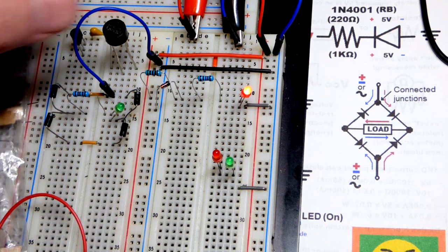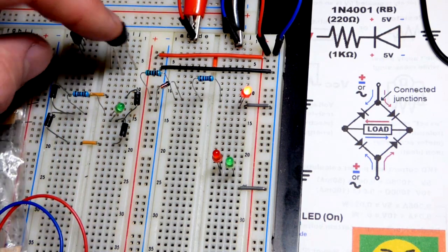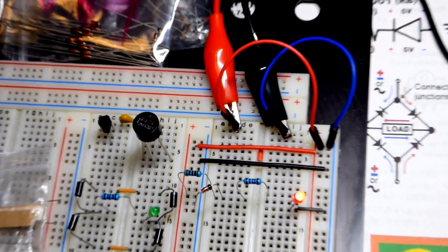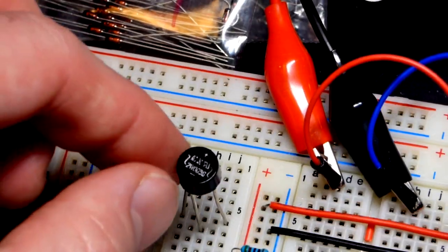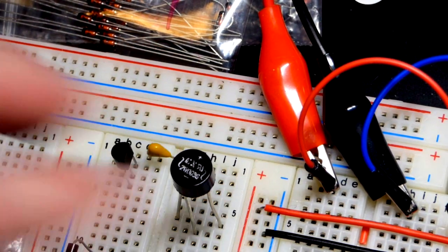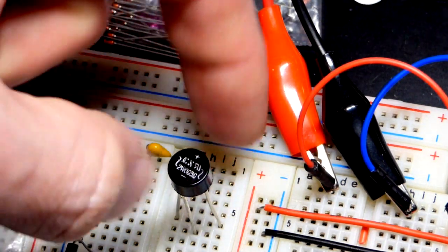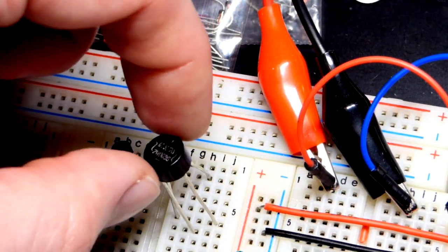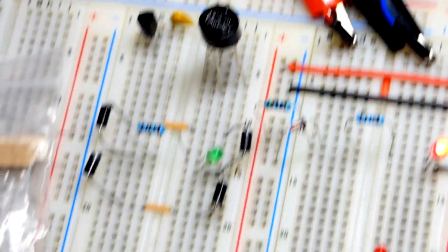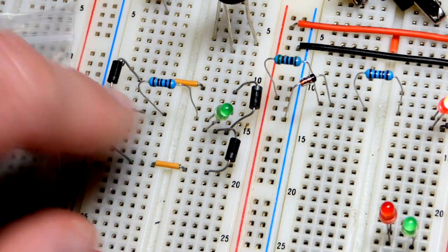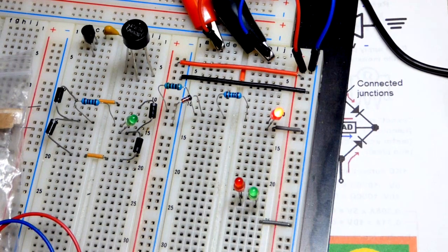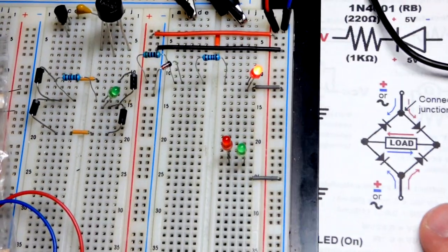There's adapters that do this for you, and there's also this component here. There's 4 diodes within here. It is a full wave bridge rectifier component. So you can see the little swiggle lines. That's where you apply your changing voltage, and you can see plus there. That's going to keep outputting plus. It's a longer lead. That side's going to keep outputting negative. So that is indicating the 4 nodes that you see there where the diodes connect on the 4 sides. And so that is the full wave bridge rectifier.